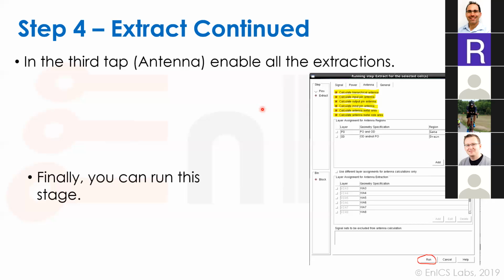One more comment, not on that, but on the LEF. I think it's actually important to sync with the place and route guide before doing the assignment of layers for the macro, because, for example, in Virtuoso, maybe you use metal 2 on the left and right sides, and metal 4 on top and bottom, for example.